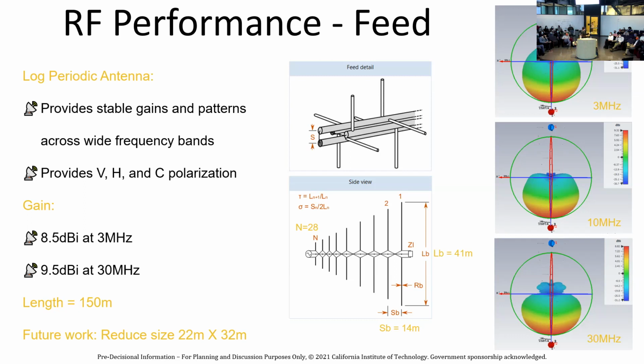But there's a problem here. There are many nice log periodic antenna designs. I saw one in your lab today that we could use. But the problem here is we don't know what the signal looks like. So we have to have a design that is so clean in RF terms that we can analytically work out what it should be doing, and then check what our results look like. Because there's no calibration source. There's nothing I can do to predict that this is what the signal should have been, and hence this is my calibration through the mesh. So yeah, we might be using a 100-meter scale log periodic antenna of that design.